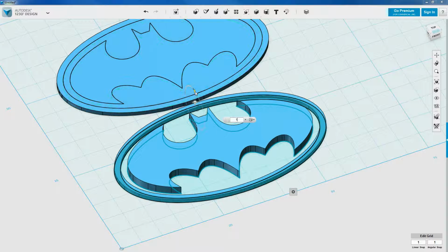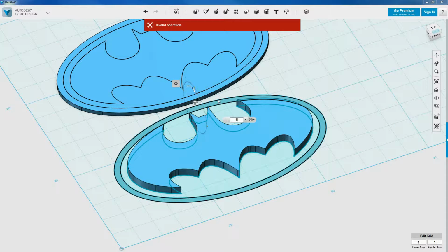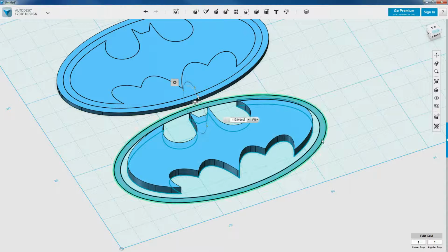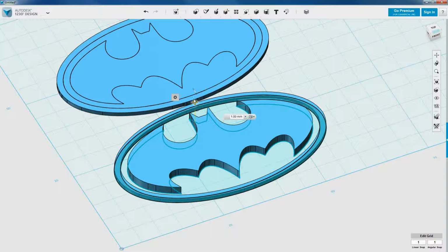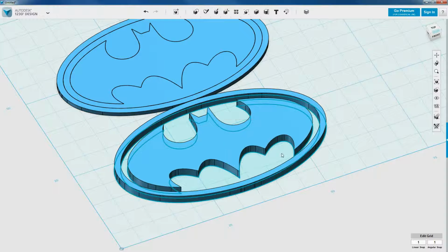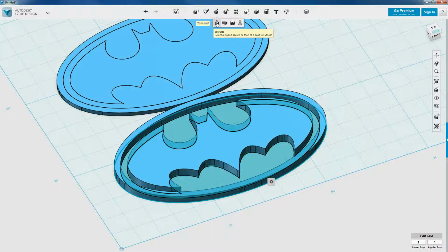Yeah, let's try this. But I'm going to put a little draft angle on here of 5 degrees. Now, is that going to work? And of course, it's not letting me play ball, is it? Okay, so I've got a slight little problem there. I'm not going to worry about that for the time being. Let's just select that. Let's extrude this up here, 2 millimeters. I was going to bring this across, but actually using draft angles does some funky things. I think just for the time being, I'm just going to select this one instead. Let's just do an extrusion here of 1 millimeter.